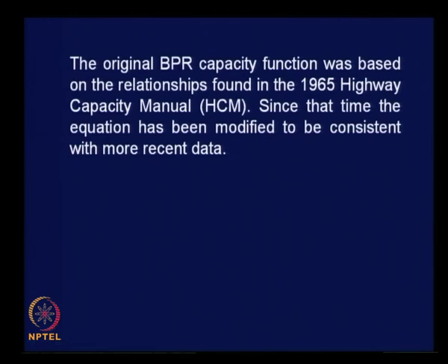The original BPR capacity function was based on the relationships found in the 1965 Highway Capacity Manual. The equation that we have seen pertains to the roadway and traffic conditions that prevailed in the 1960s. Since that time, the equation has been modified to be consistent with more recent data.